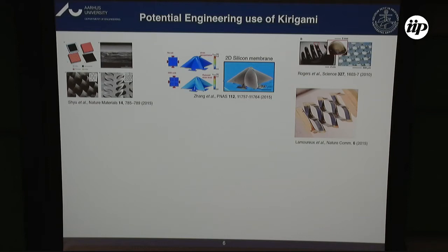People have been doing this etching of silicon wafers, and they are able to carve out some of these Kirigami structures, and for whatever interest they might have, like I showed you here, for large strains of these structures that are usually stiff. Or to avoid types of localization like this, where you have cuts that are made, and then you can reduce some unwanted forms of localization on your thin sheet.